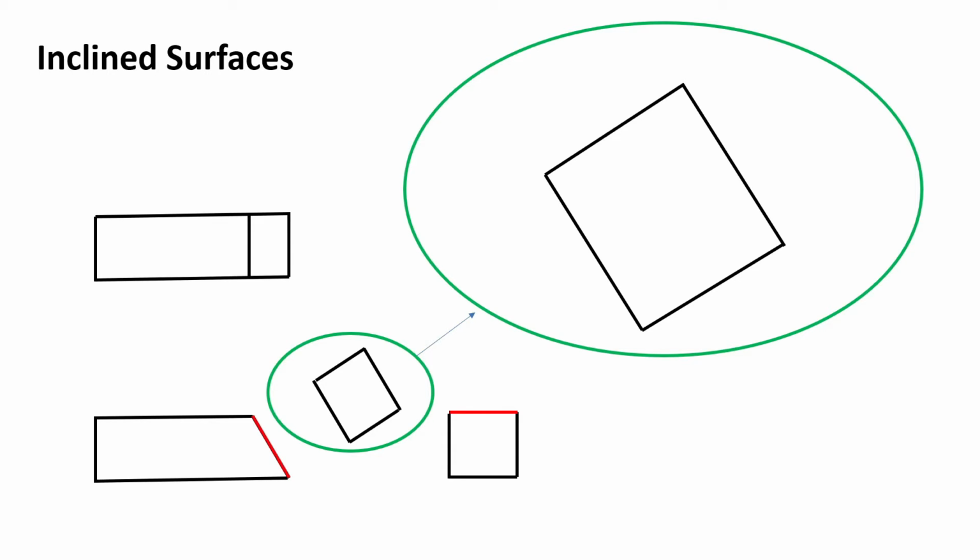Obviously, there are far more complex surfaces that must be explained by means of auxiliary views. However, if the rules that have been demonstrated here are followed, auxiliary views can be used consistently and reliably to provide the necessary information to create part features.